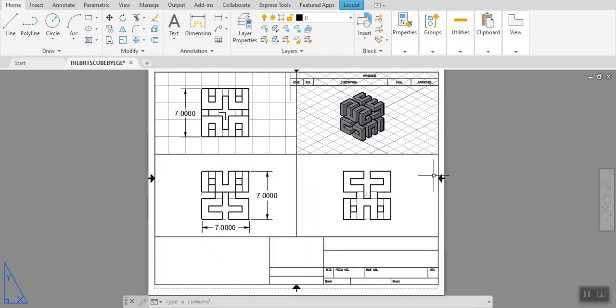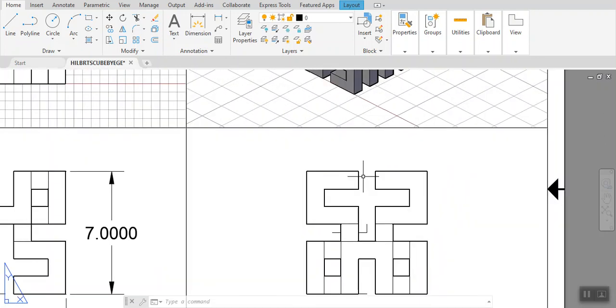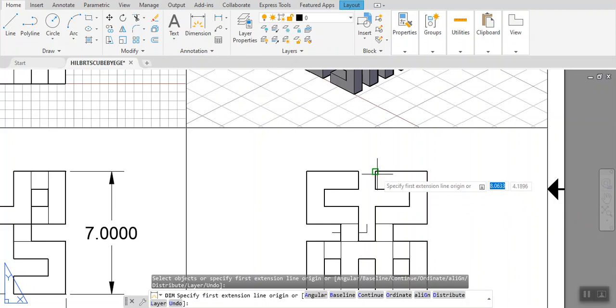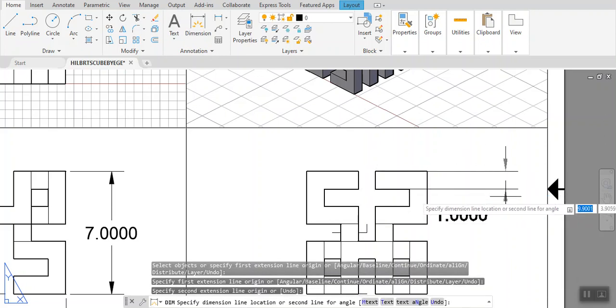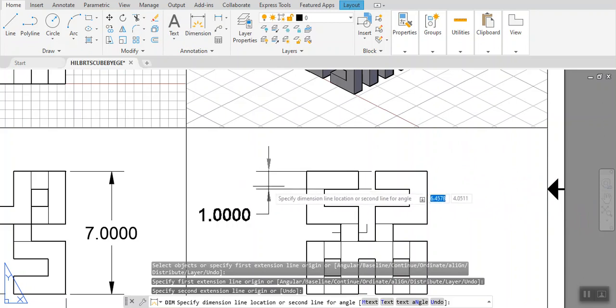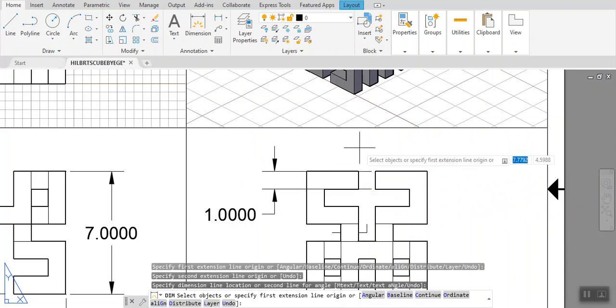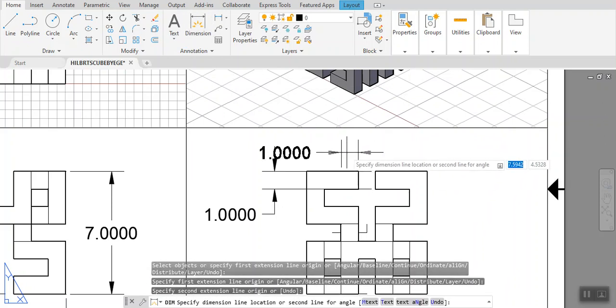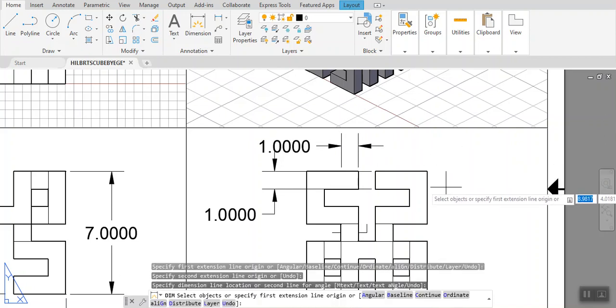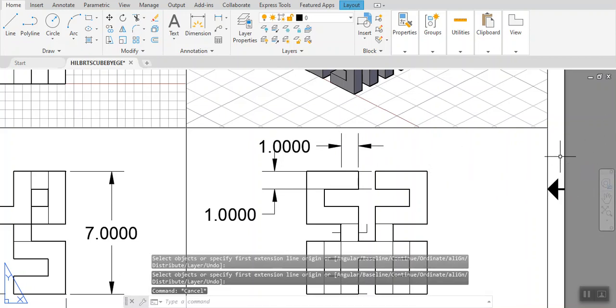Maybe a few dimensions will help. Definitely. It's the typical dimensions. That's 1 inch. Each one of them is made out of 1 inch. So you may want to click in here, click here, and then take it outside this way. This is a typical dimension. You want to give that. And another dimension, perhaps from here, here. That's another typical dimension. And now escape.